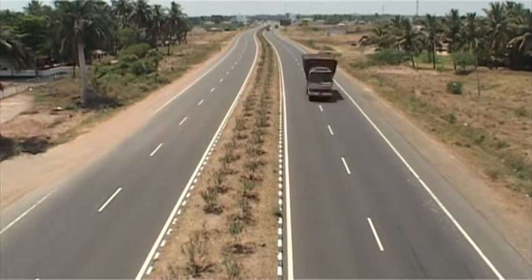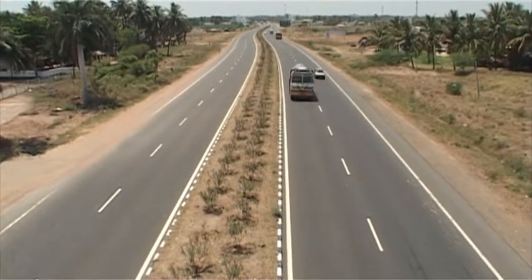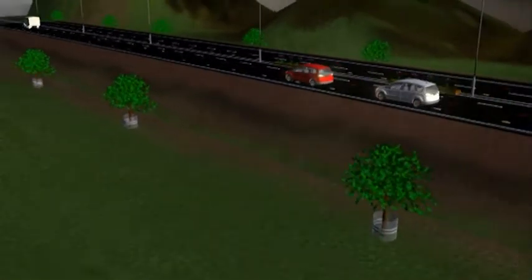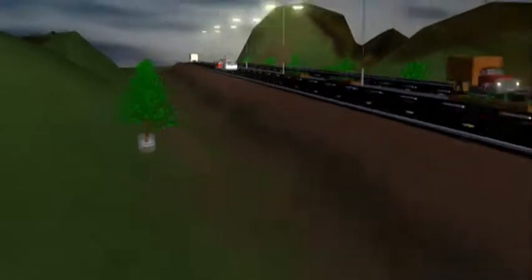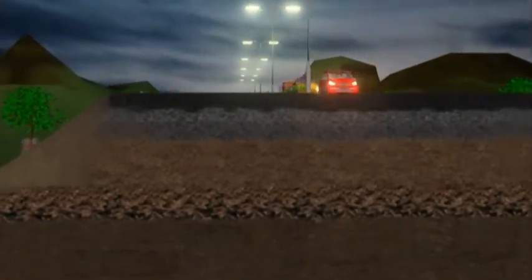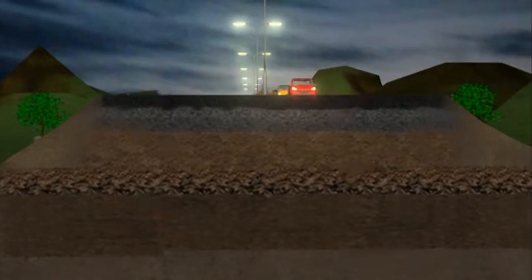Highways are subjected to high levels of traffic stresses regularly. The vertical compressive stress is maximum on the pavement surface directly under the wheel load and is equal to the contact pressure under the wheel. Layer system concept was developed for stress distribution on the flexible pavement.